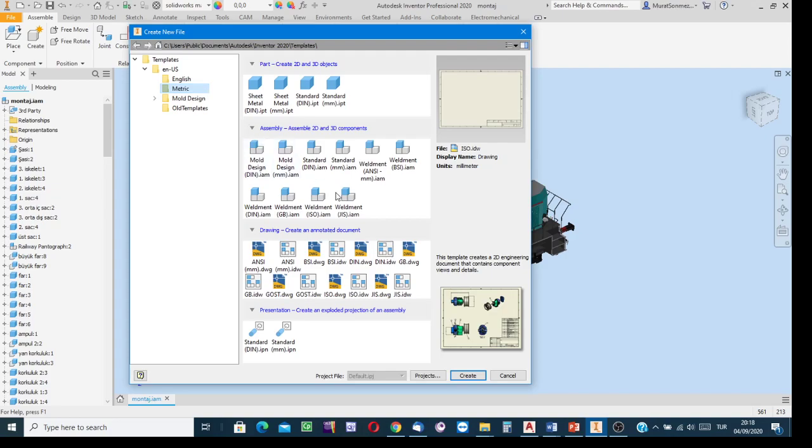When selecting the metric unit system, I selected the first quadrant. Then bring the cursor onto the template option. If the software is Inventor, not AutoCAD but Inventor, then unless otherwise requested, create the views using the Inventor template, so the file is in Inventor format.